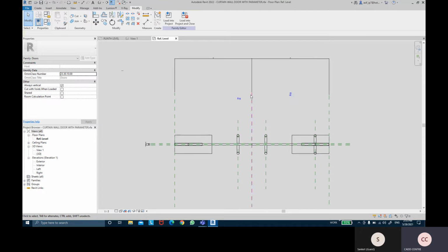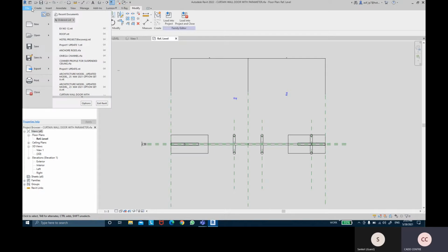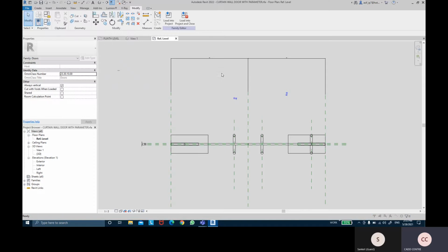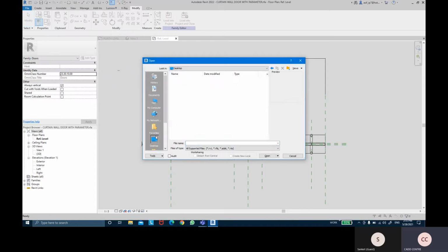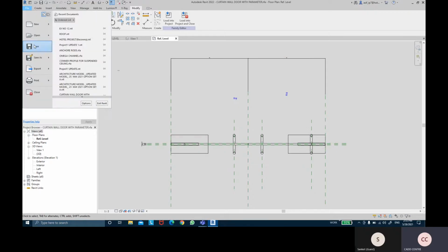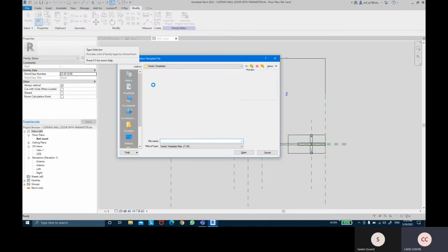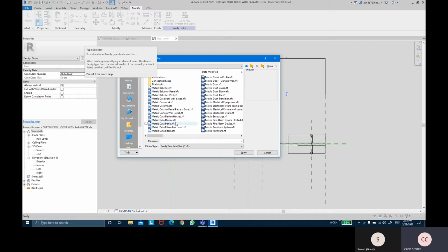Okay. I'm going to make the first one for the single panel 2D detail. So let's create a family. If we already have one, we can use that family as well. I have deleted it, so let us recreate it quickly. New family, English. I'm going to take door, but curtain wall door actually.